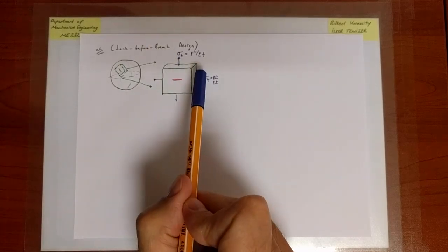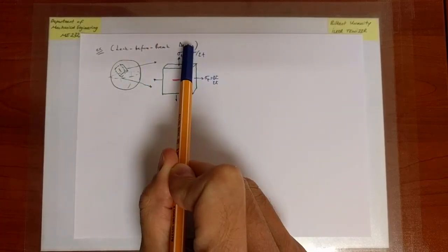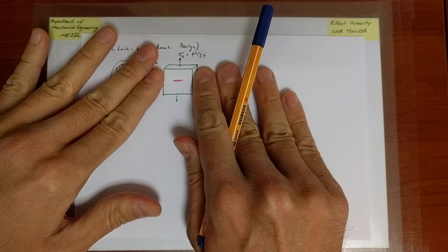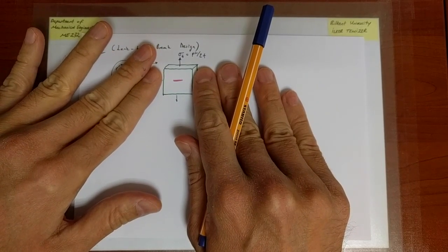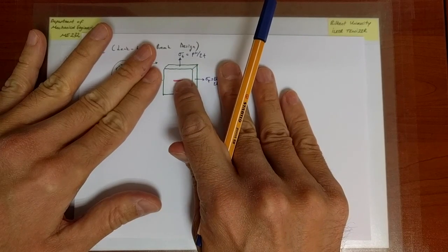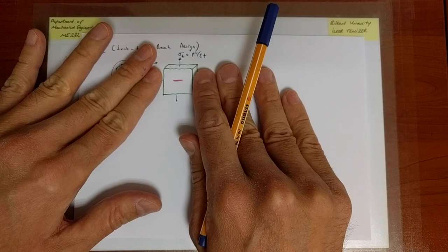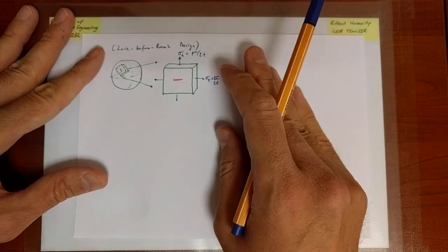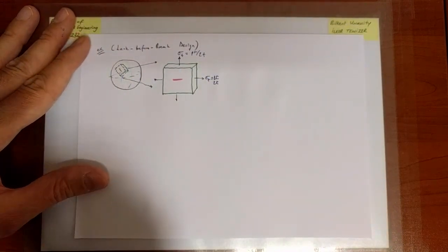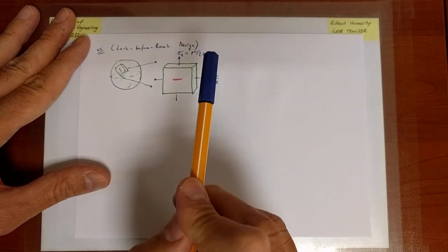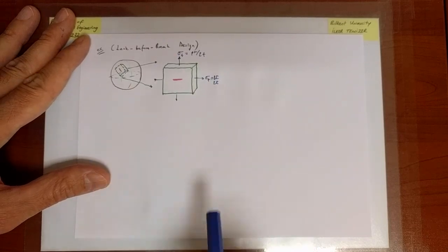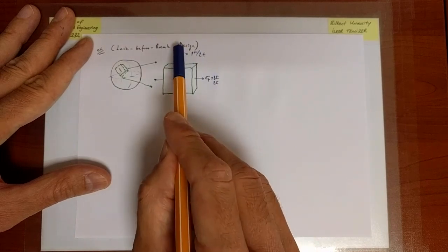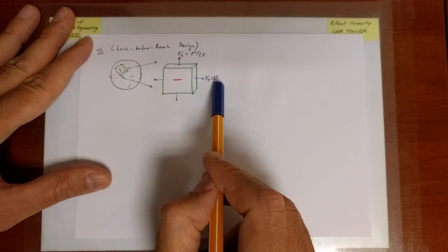Now, eventually I'll do a fracture analysis here. And if I did not have these tangential stresses, the horizontal normal stresses, it looks like my ideal prototypical plate with a central crack, irrespective at this point of the geometry of that crack, which is also important. If these are not there, then the situation is identical. But we do have a normal stress in the other direction as well. So in general, the way you load your structure is important. Whether or not there are tangential stresses here is important. But it turns out that in this case, these tangential stresses are equal in both directions. So this normal stress is equal to that value.